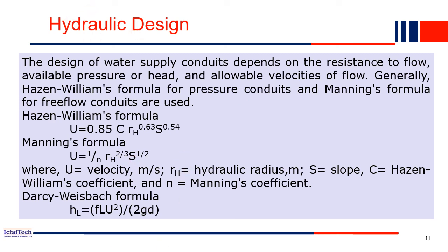Hydraulic structure means, let me draw it here. So for example, here you have the river, right? So from there basically we are collecting, so we have the intake structure at the middle of the river, and through a pump basically we are pumping the water to the water treatment plant. So here we have the water treatment plant, right? And we already know how much water has to be treated for this water treatment plant, because through population estimation, forecasting, and all, we already know that in the city where the water will be distributed, how much water has to be treated every day.